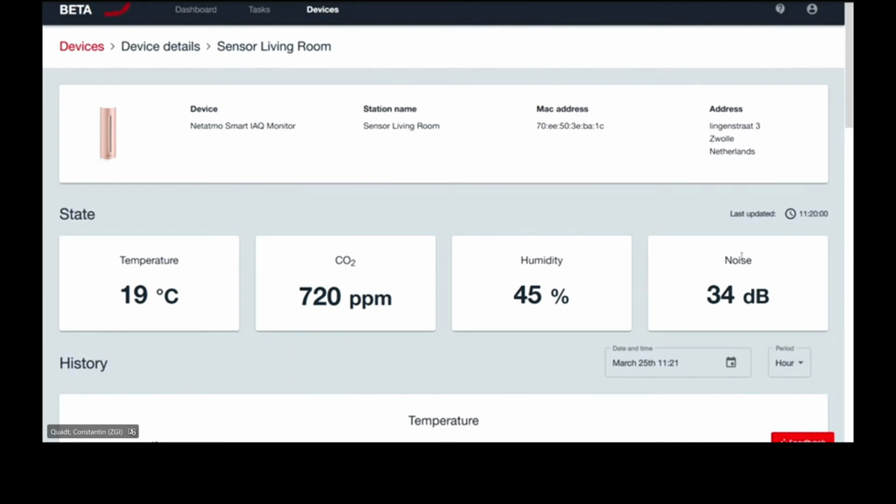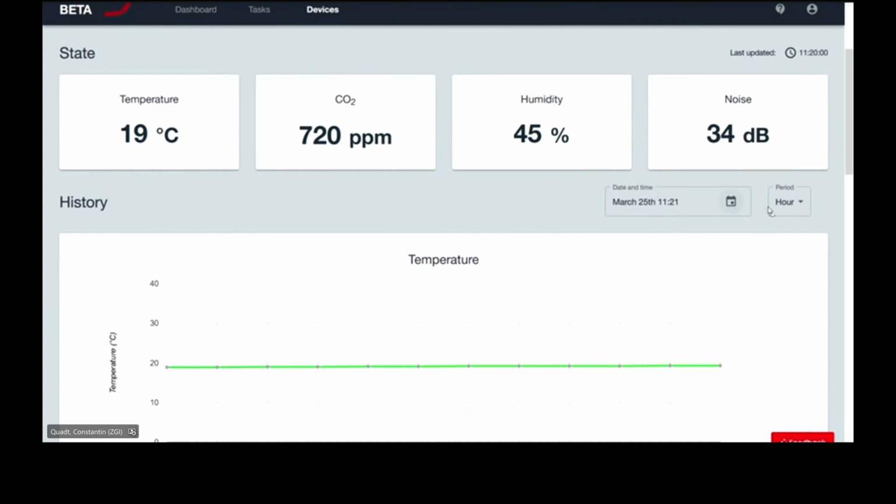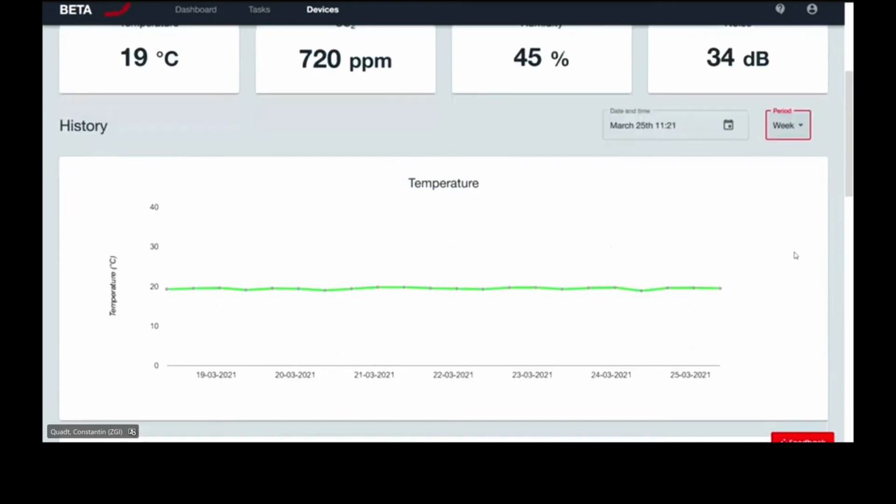What this additional device gives us is the ability to monitor our indoor climate in one specific room. We did this in this case with a family, and what we monitored and detected was a very interesting use case and behavior. This family regularly gathers for dinner in the evening. On Friday nights, the 2 children who are already at university come back home and join the dinner. Then we can detect a peak in the CO2 levels, and our installed ventilation unit didn't quite cover this. So we would need to actively increase the fan speed to level out the CO2 increase on Friday nights.